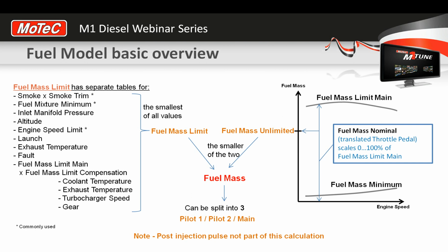Now if you make the number in this table too big and you put your foot down and there's not enough air in the cylinder, the boost is very low, and you apply too much fuel, you'll fill the street with smoke. And that might be okay for some of you, but the majority, and certainly parts of the world where we live, the majority of people want to try and reduce or minimize the amount of smoke. But other than that, you won't have a problem.